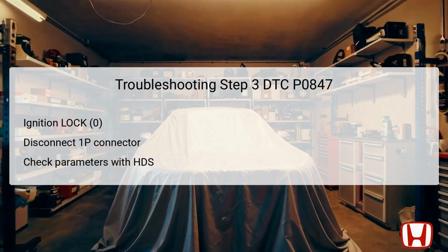In troubleshooting step 3, technicians must turn the ignition switch to the lock 0 position, ensuring all electrical components are powered down before proceeding. This safety measure is crucial during electrical diagnostics.